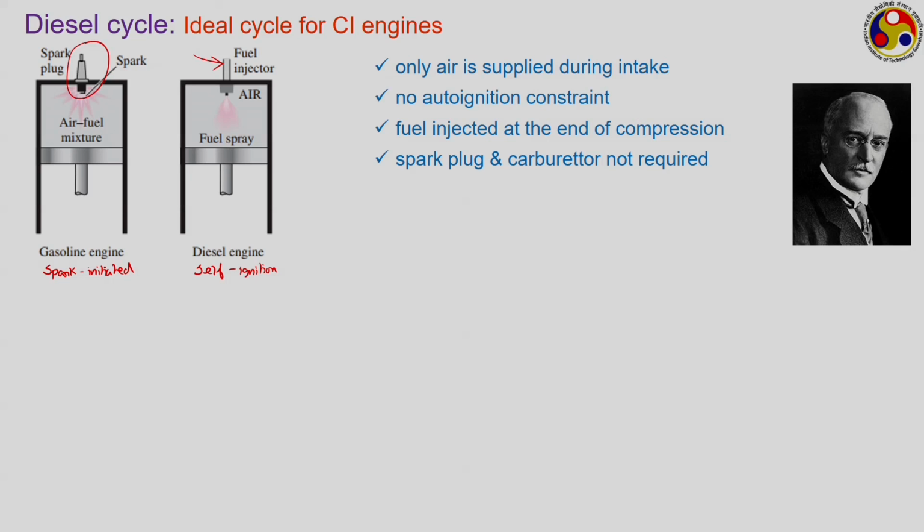Then spark plug and carburetors are not required, because we do not need to produce any spark. Spark plug is not required and carburetor is required only to prepare a fuel air mixture. Now, as we are not preparing fuel air mixture, air is supplied at the beginning of inlet process and fuel is sprayed after the compression process. So, carburetor is also not required, but of course, we have a fuel injector and we generally also need a fuel pump, because the pressure of the fuel needs to be higher than the pressure of air for it to be sprayed inside. So, we need a fuel pump and a fuel injector or spray gun, which are in fact much costlier and heavier compared to the spark plugs and carburetors, and a higher compression ratio, as I have mentioned.